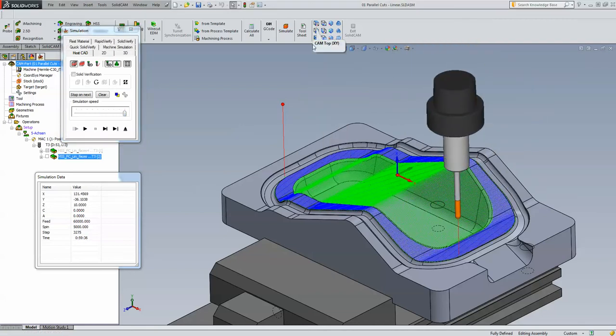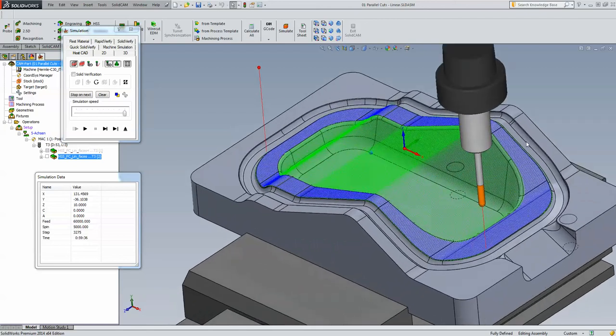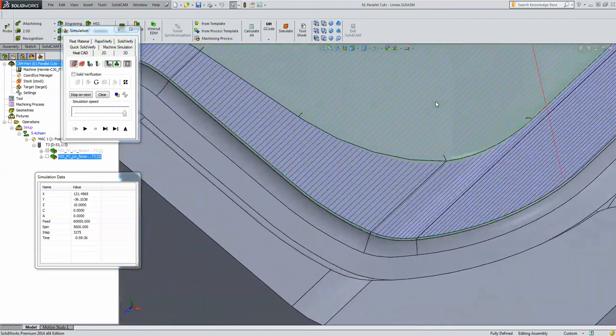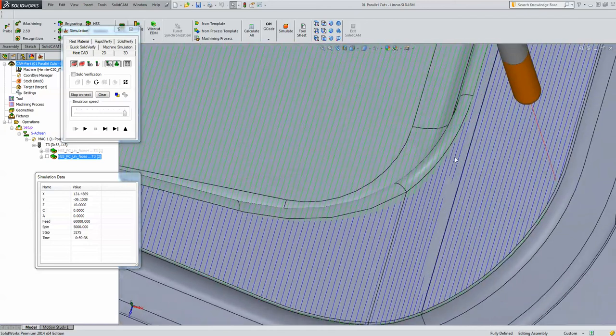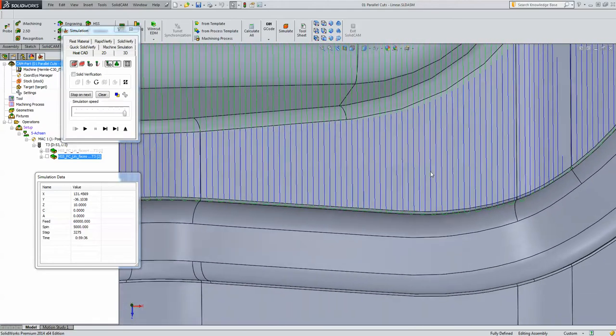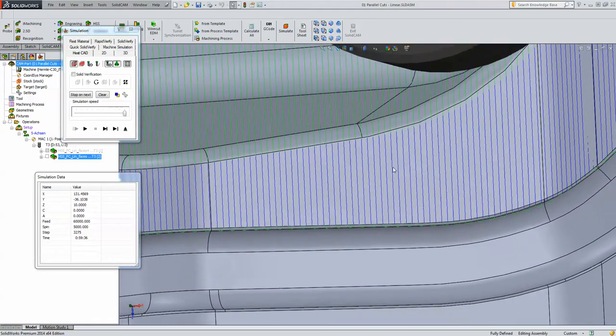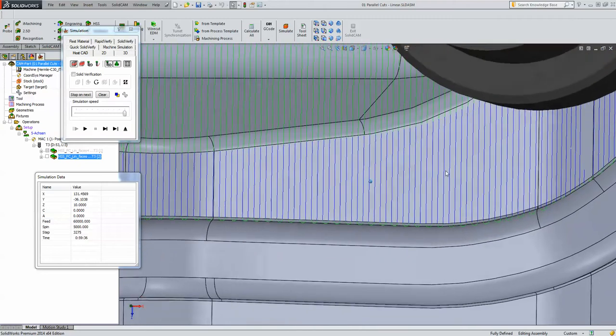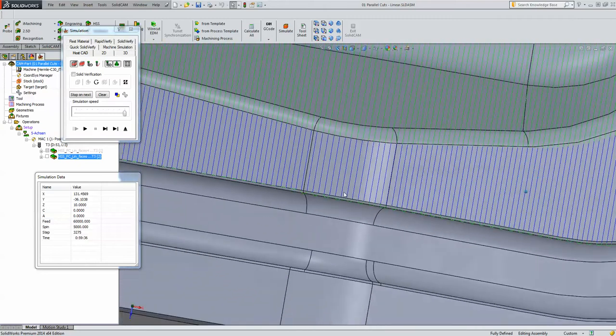If you see the way it looks right now, this actually looks a lot closer, the steps, to one another, and this flat surface also looks closer than it is over here. But if I were to zoom in to the actual toolpath itself and try to be normal to that particular surface, you can see as I'm going around the part, and now I'm normal to this surface over here, you'll see it's actually very even as it's going around the part itself.